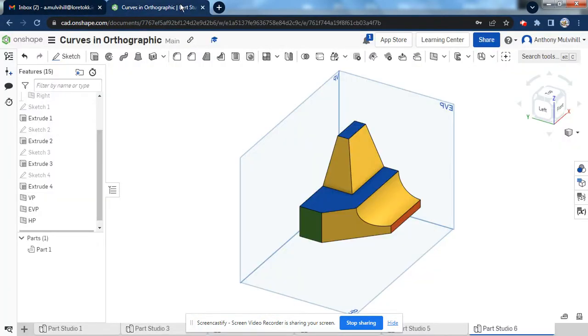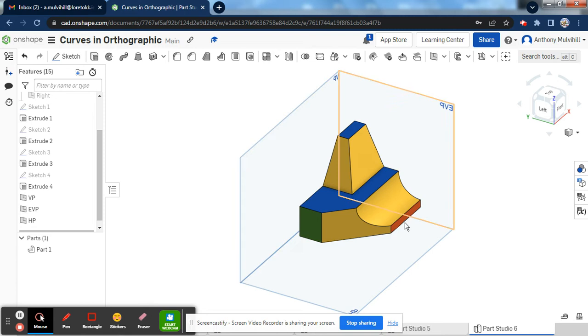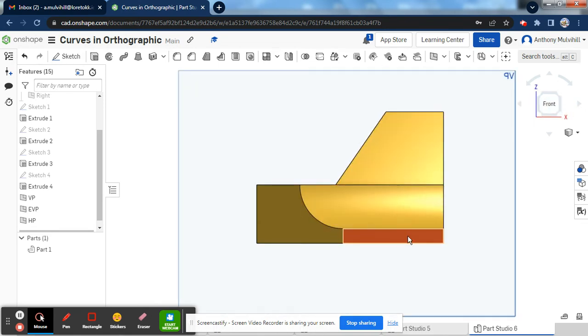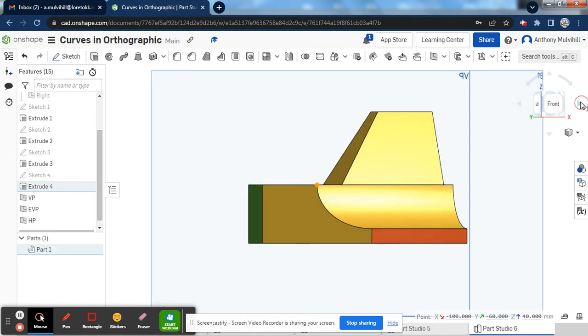So I'm just going to go to a little model view here. We can see here in the direction of arrow A, I'm going to go here to my front view. And this is what we're going to see. This red surface, this yellow slanted surface, here's the curved face, and here's the bit at the front. This point right here is the bit that we might struggle to find at the start. We'll only be able to get that in our plan view. And even though it looks almost like a perfect quadrant of a circle, that surface there we're actually going to have to sketch in using point location.